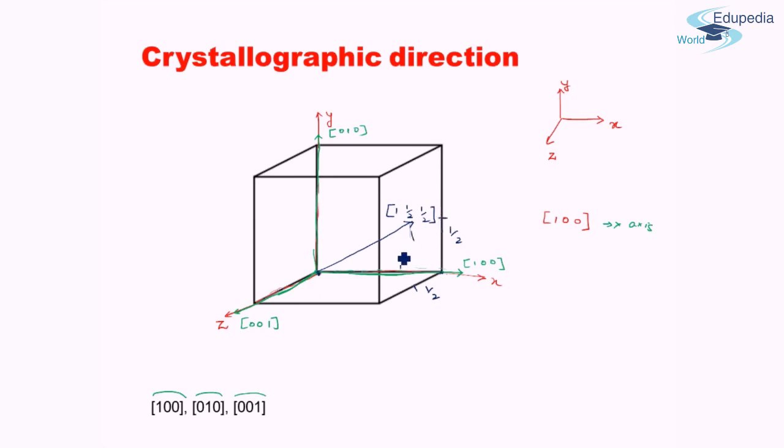But as I had said in the algorithm, this is a matter of convention, that we do not keep fractional Miller indices. We do not keep fractional Miller indices in crystallographic direction. So what we will do is, the half needs to be converted to the nearest integer. How can we do that? We can do that by multiplying by such a number that all the fractions get converted into integers. So if we multiply all 3 indices by 2, then we get 2 1 1.